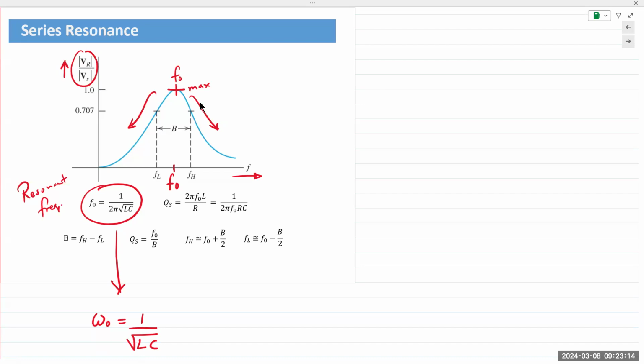That's just normalized. It's a normalized ratio. You've done the lab, right? 251. So in 251, the plots that we are plotting are not the transfer function versus frequency. We plot V out versus frequency. So with graphs and charts, you can take the data and decide what you wish to use according to your application. Plotting the transfer function, like a normalized transfer function, is kind of standard. It makes it easier to compare.